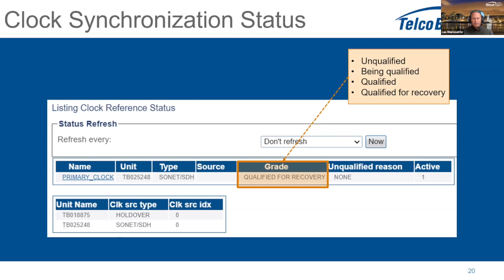When the unit here is removed from the system, the clock source will then be captured by the other device here. And since we're using holdover, even if there's a clock change, it doesn't create a glitch in the system. The clocks are slowly drifted to the new clock if there's a change in frequency.